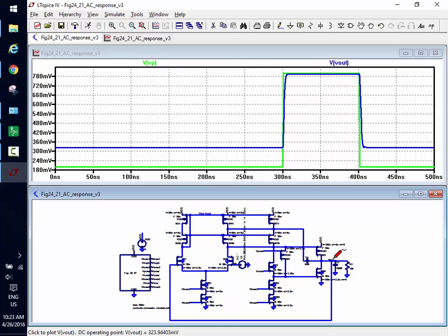You see there, the output's not going all the way down because the NMOS, well, you tell me, why isn't it going all the way down? Because I can't go below the... Yeah, because the NMOS diff amp shuts off. Does everybody see that? Anybody not follow this? Any questions? I don't want this to be magic. You're designing a real op amp. I want you to know what the limitations are.